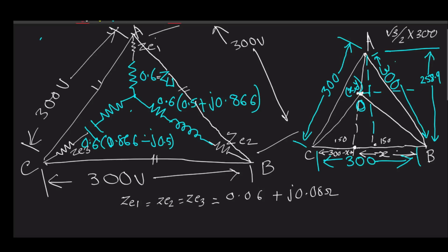Now we have to express all the voltages in terms of neutral. Why is this O so important? Because in this diagram, if you try to locate O, here it is. Once we can find out the voltages between A and O, B and O, and C and O, then we can divide those voltages by the corresponding phase load. Phase load means total load, comprising the series parameter as well as the load value.